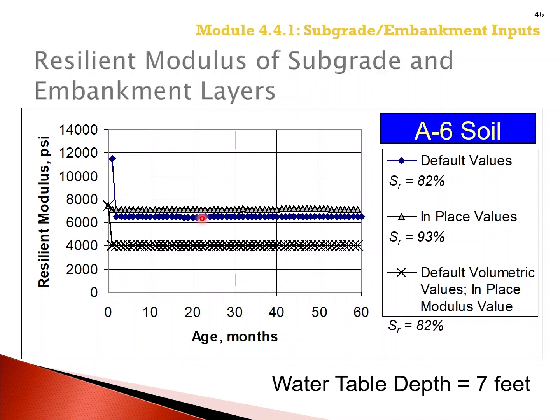Now, if a CBR value was measured for this A6 soil on test specimens, but only after soaking, in other words, the soil is allowed to increase in water content and then the CBR test is run, the CBR value is representative of a soak condition.